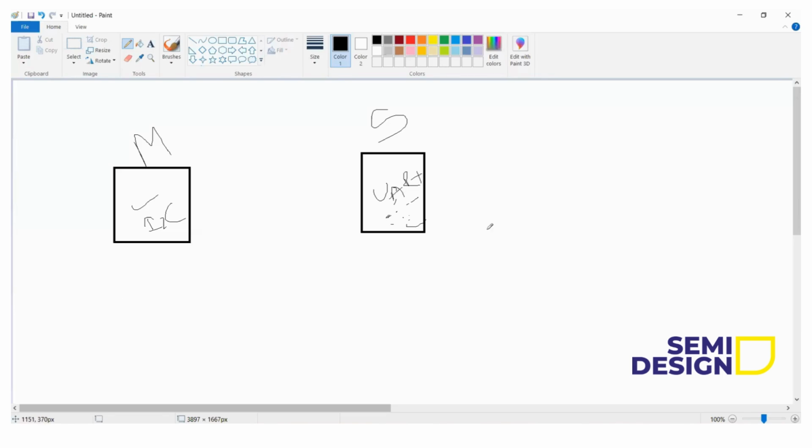So for this, I need an interface protocol. Interface protocol means this AMBA protocol. In AMBA, I have APB, AHB, AXI. Which one should I use here? Remember, whenever you are dealing with low speed, go for APB. APB is used for low speed. So here there will be one APB bridge. Now you have to convert the I2C pin to the APB pin, then the APB pin to the UART pin.